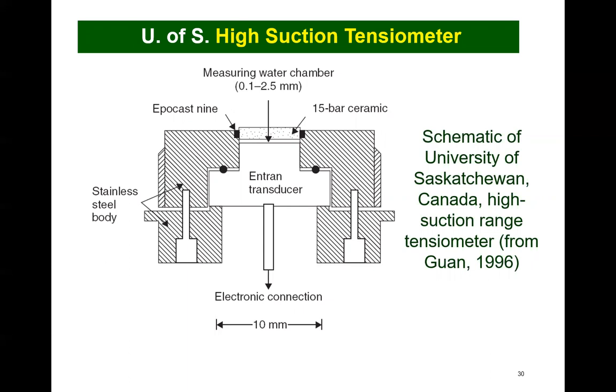The water in the compartment below the 15-bar ceramic disc is initially serviced through the use of a cycling high pre-pressurization of the water. These tensiometers work quite well in the laboratory, but need to be reserviced following a cavitation.